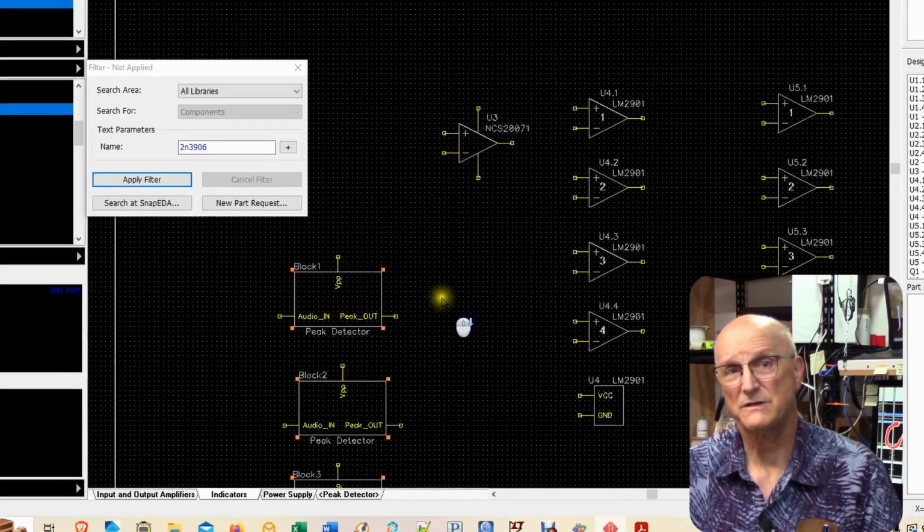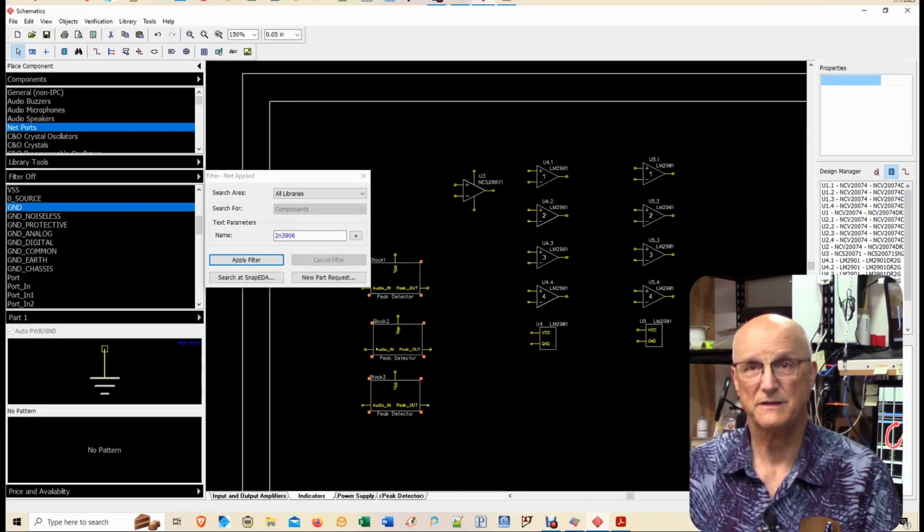Now, we have to start organizing the parts on the schematic. We remember as we place components on the schematic that we want left to right, top to bottom signal flow. So our 3 channel inputs will be at the left of the schematic. Now we have to think about connectors.